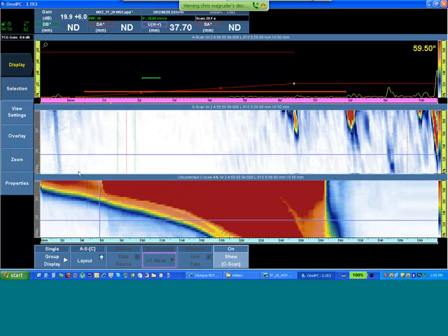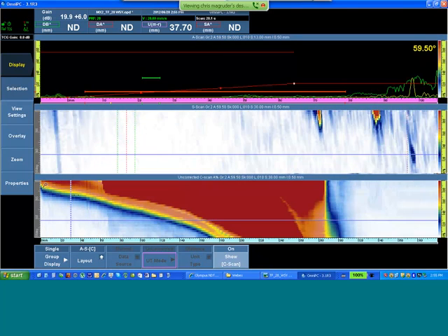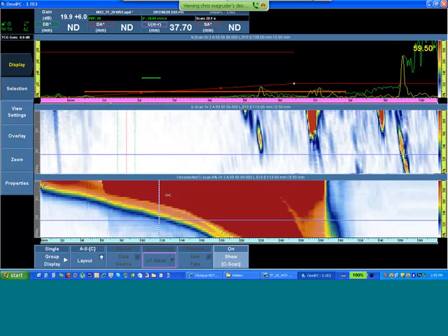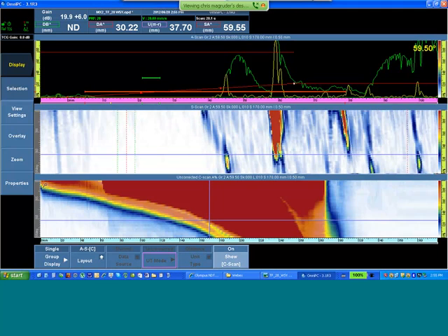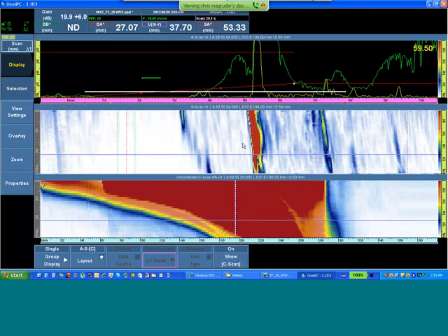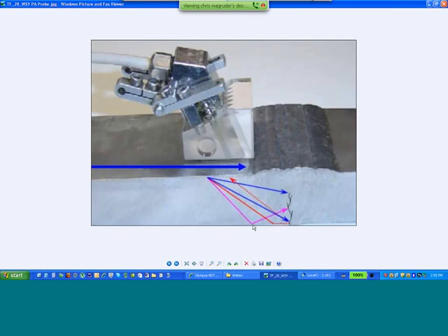And this is an example of where the S-scan is going to use a sound path display, meaning the range is exactly the same on all focal laws. This represents me walking the probe slowly towards the weld. As I move towards the weld, the base of the crack or the corner trap starts to appear here, and the tip of the crack appears here. As I continue walking that into the weld, this big signal is the mode converted shear wave skipping into the crack here. It's traveling at a velocity of half the speed, so it appears farther in time of flight.